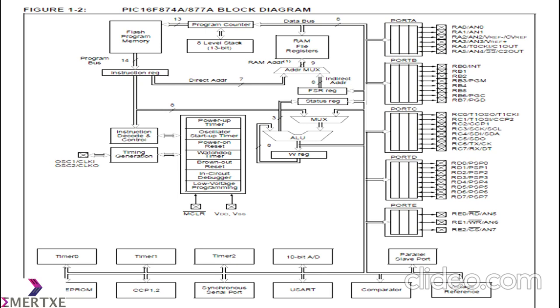The PIC16F877A is a microcontroller. Here it has the following components. It is a 40-pin dual inline ceramic core with the 40 pins as follows. This has been classified into port A, port B, port C, port D and port E. Port A consists of 6 pins, port B consists of 8, port C consists of 8 again, port D consists of 8, and port E consists of 3.